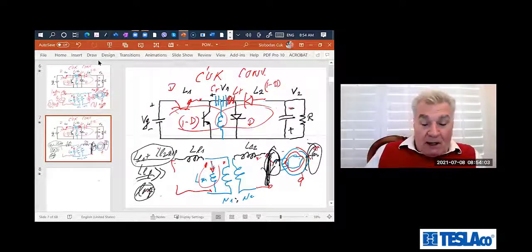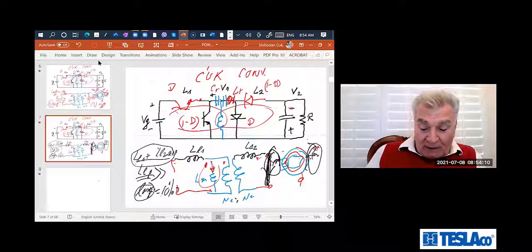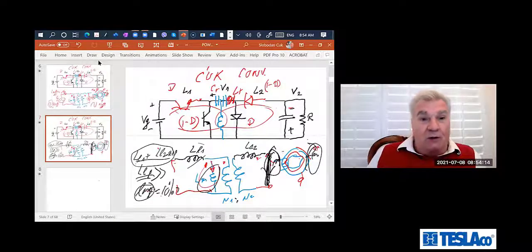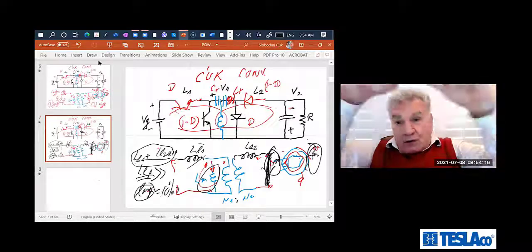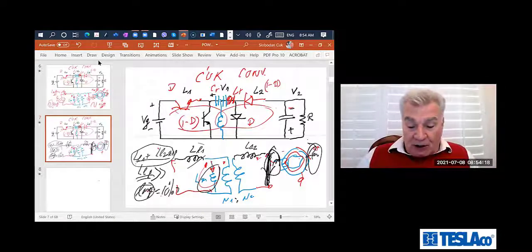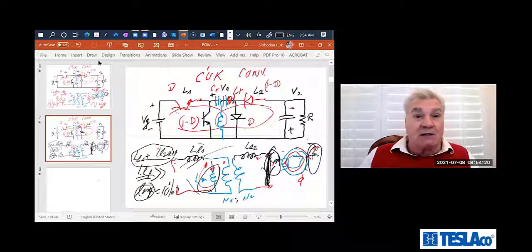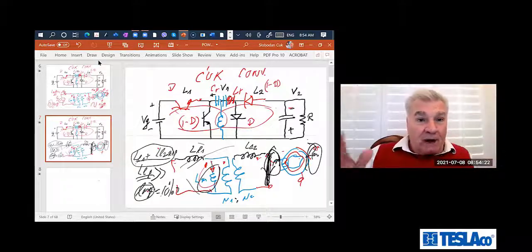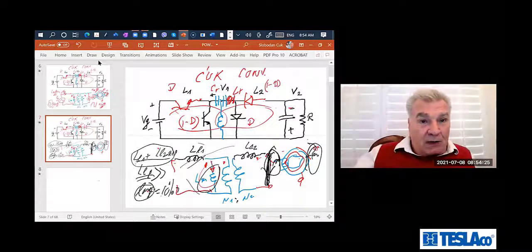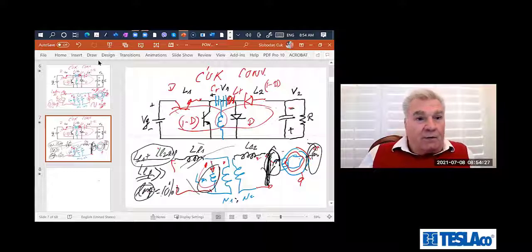So what they actually wanted was for the leakage inductance to be 10% or more of the magnetizing inductance, because leakage inductance will be the only thing during the short. There will still be inductance in this loop which will hold it enough before it's saturated completely, so that you can turn off with a circuit breaker. So that's one reason.